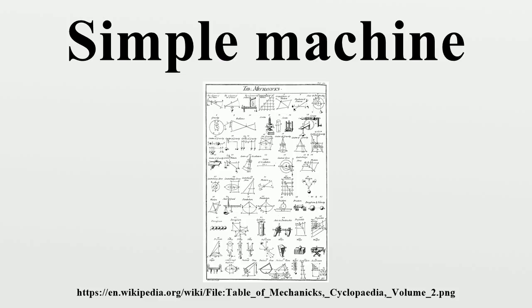Modern machine theory. Kinematic chains. Simple machines are elementary examples of kinematic chains that are used to model mechanical systems ranging from the steam engine to robot manipulators. The bearings that form the fulcrum of a lever and that allow the wheel and axle and pulleys to rotate are examples of a kinematic pair called a hinge joint. Similarly, the flat surface of an inclined plane and wedge are examples of the kinematic pair called a sliding joint. The screw is usually identified as its own kinematic pair called a helical joint. Additional links can be attached to form a four-bar linkage or in series to form a robot.